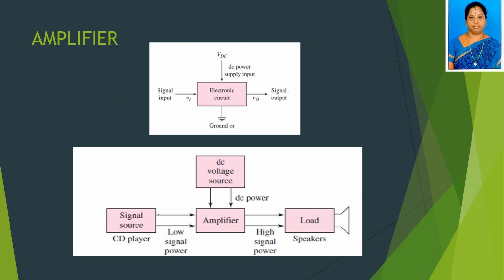But DC voltage is always 10 volts, 5 volts, 25 volts. When compared to the signal source, it is larger. DC voltage is on the order of volts, signal source is on the order of millivolts. So that's why analysis only with the signal source is called a small signal analysis. The analysis of the amplifier only with the DC source is called large signal analysis.